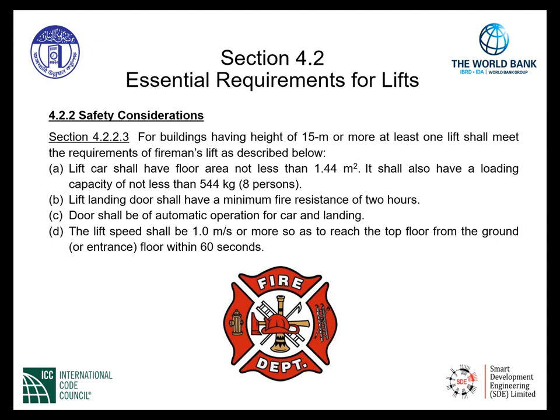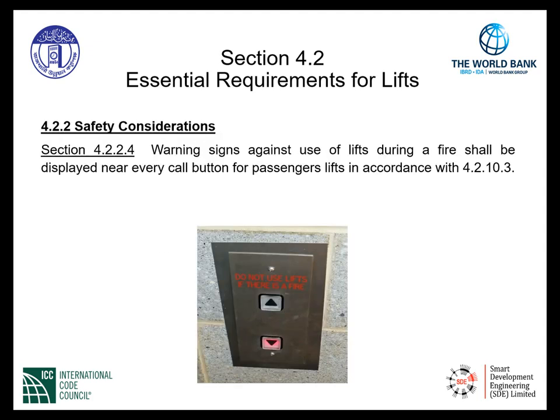B. Lift landing door shall have a minimum fire resistance of 2 hours. Item C. Door shall be of automatic operation for car and landing. And finally, item D. The lift speed shall be 1 meter per second or more so as to reach the top floor from the ground within 60 seconds. Again, this is specific requirements for the fireman's lift.